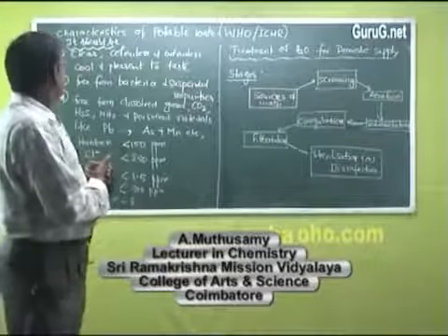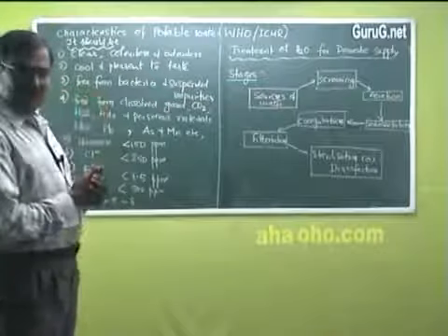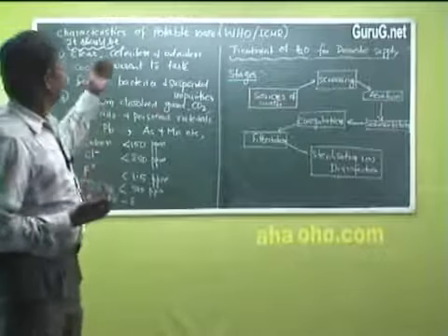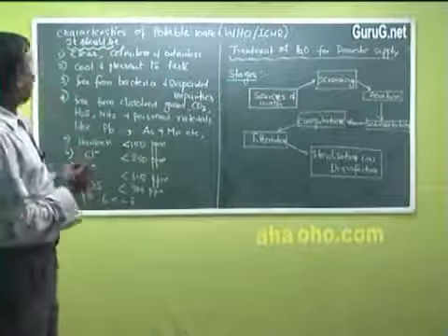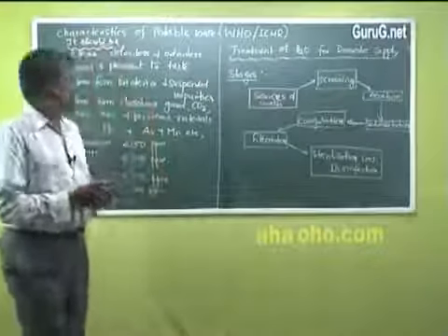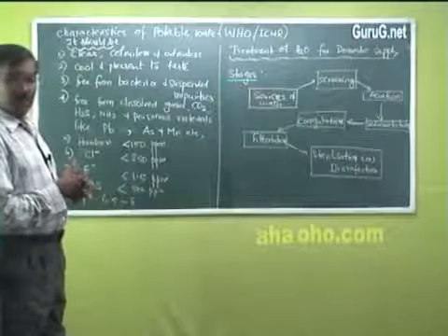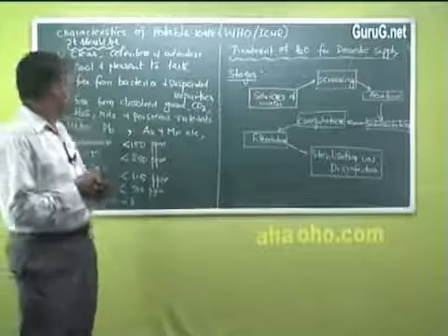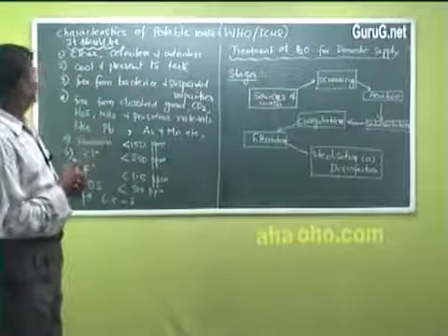So a list of characteristic parameters to be possessed by potable water, that is water supplied for domestic purpose, which are prescribed by WHO and ICMR. The water should be clear, optically clear. It should be colorless, odorless, cool, pleasant to taste. So the temperature is very important for water. Free from bacteria and suspended impurities, which are very important for a good potable water.